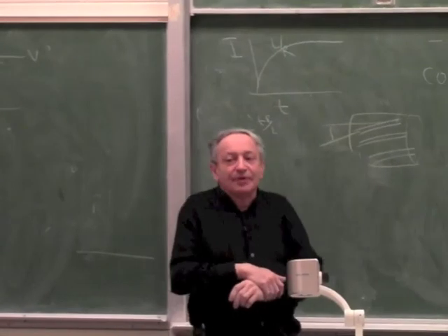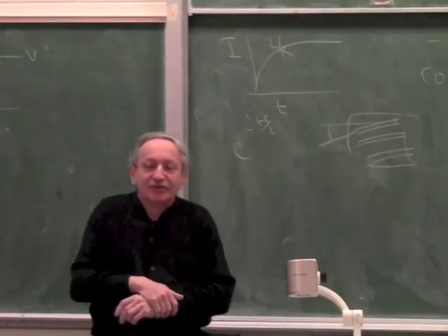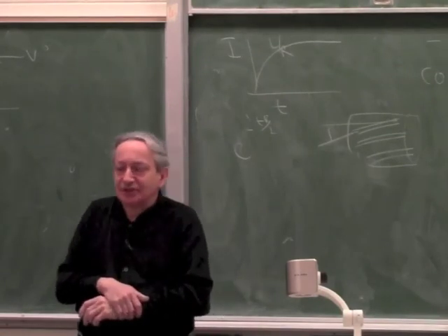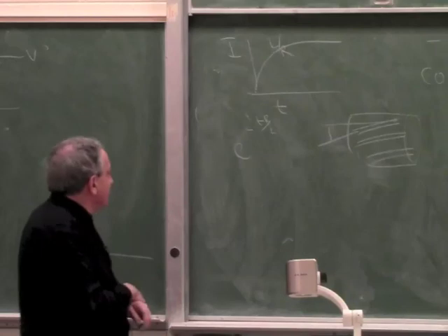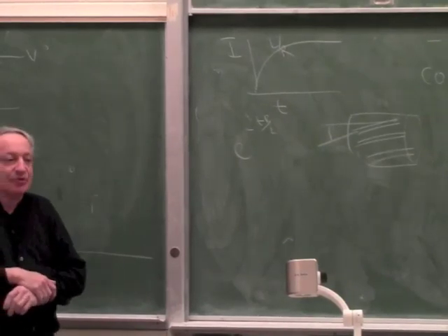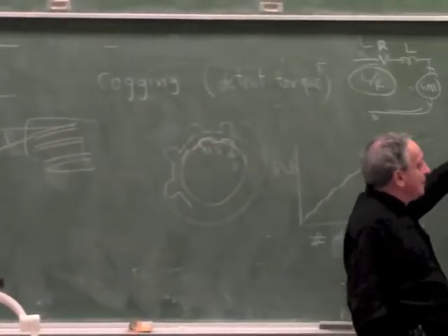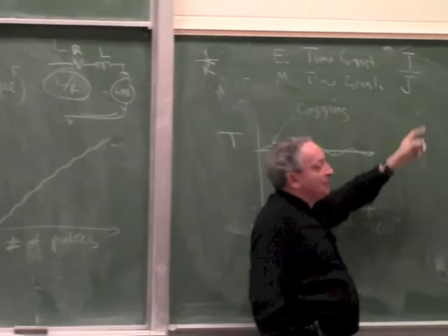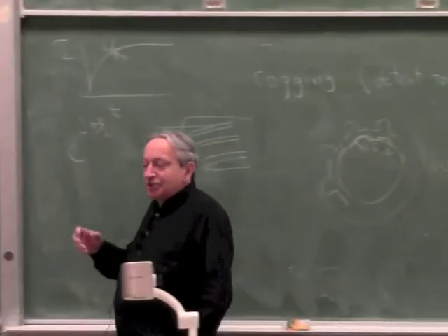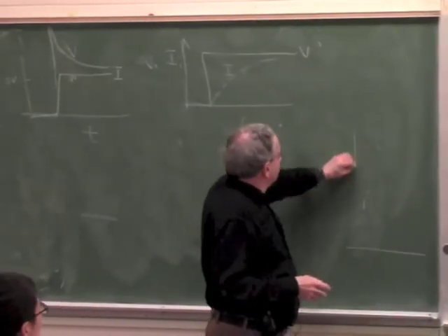Okay, now if motors are designed for very high performance servos, they also have a different construction, because if you look at the typical PMDC motor, you want to minimize inertia, that is, maximize the torque to inertia ratio. So if you look at the armature of the motors I showed you, they had a piece of steel.